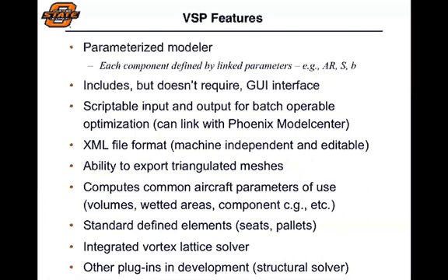Now, again, it does have a lot of other features. There are some standard defined elements that come with VSP, so you can start putting certain things in like engines and propellers, and do that very, very quickly, like you couldn't do in a CAD program since you'd have to define those from scratch. Airfoil profiles are often pretty difficult to put into CAD programs. Very difficult to draw an airfoil because it's got a unique leading edge, unique trailing edge.